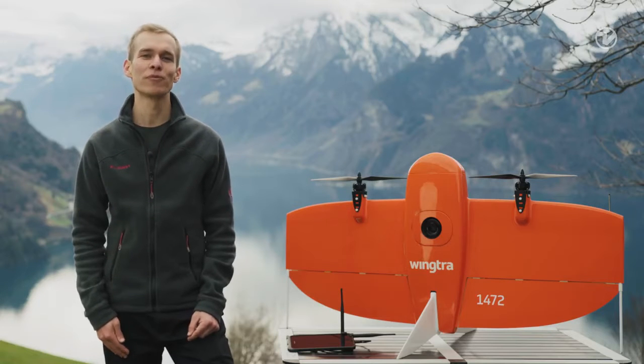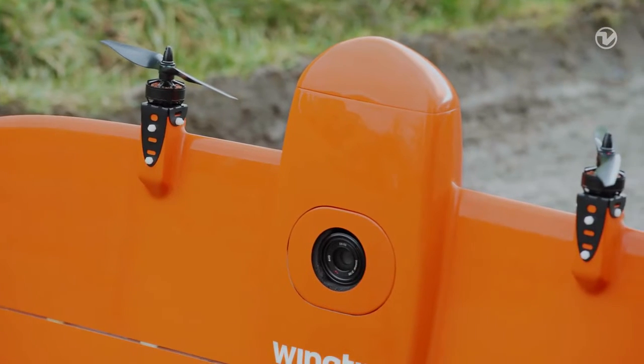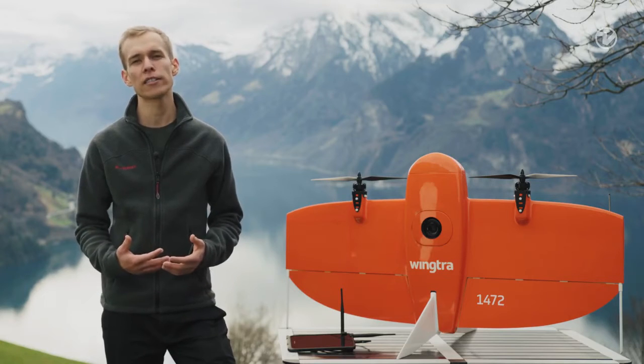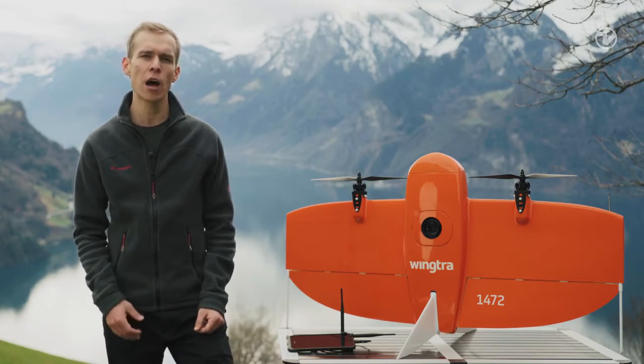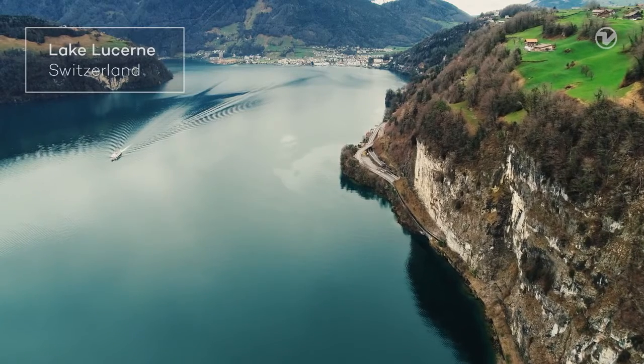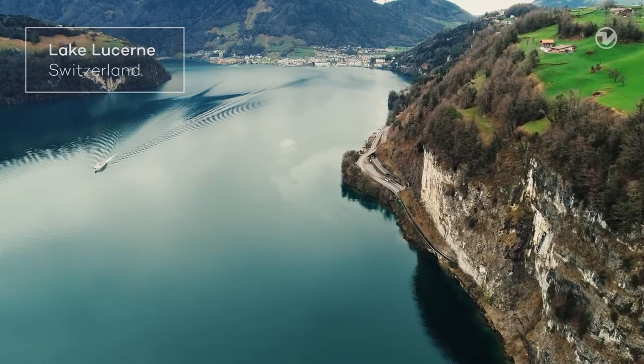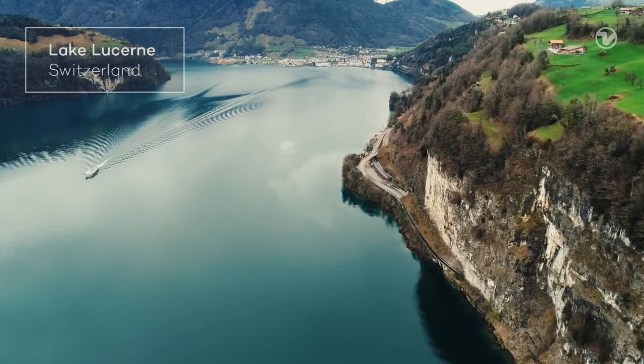Hi, I'm Julian. Today we will do a survey with the WingtraOne surveying drone. You will see how to plan a flight, how to collect aerial images and how to safely interact with the drone at any time. Below us along the lake there is a road. Our job is to get an accurate map of the road itself and of the mountain on top of it.